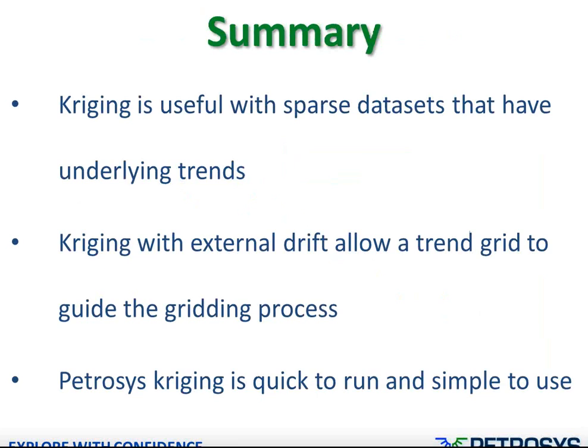So just to summarise today's webinar, Kriging is really useful and is worth considering when you've got sparse data sets that have underlying trends. So if you're gridding well data or 2D seismic, then Kriging is worthwhile having a look at. Kriging with external drift allows you to use an external trend grid to help guide the gridding process. You can do this with any variables. So you could be doing depth with two-way time as we've done today. You might have an amplitude grid that correlates with porosity. You might have a stacking velocity grid that correlates with well velocities, etc.